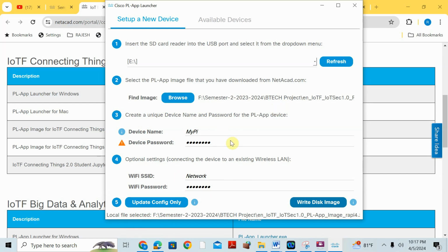Before that also they will ask, do you want to overwrite the content of the SD card? Yes or no? Give yes. Just wait for a few minutes. After that we'll go for how it will be written, because we cannot wait for 15 or 20 minutes to get the image written. So I will wait for the unzipping to be done and then go for the final output after you write the image. Sometimes this unzipping will take some time, so that's why I just recorded everything here.